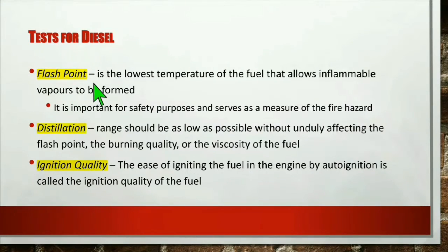Flash point is the lowest temperature of the fuel that allows inflammable vapors to be formed. It is important for safety purposes and serves as a measure of the fire hazard. Distillation. Range should be as low as possible without unduly affecting the flash point, the burning quality, or the viscosity of the fuel. Ignition quality.